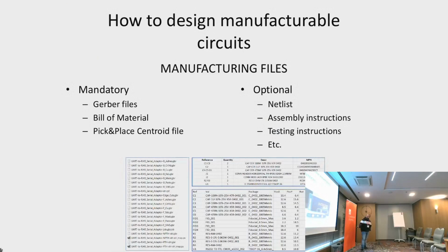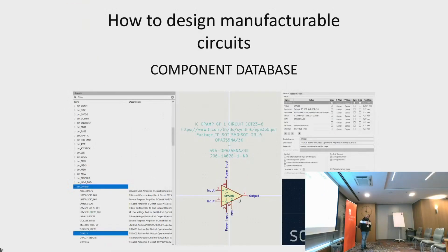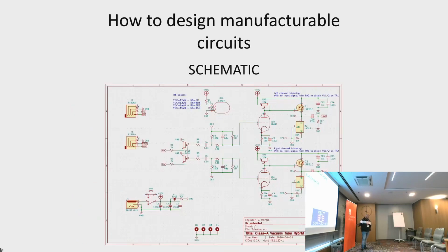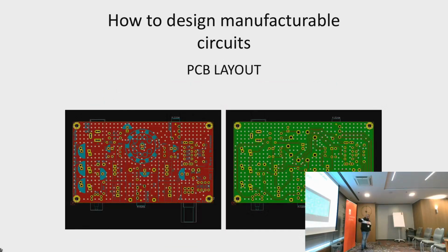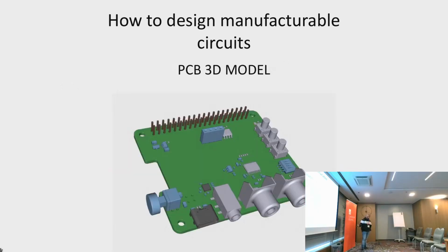Yeah, I forgot to mention that. Let's go back. In the footprint editor, you can attach a reference to the 3D model of the component. That is taken later on by the layout tool, when you can export the complete 3D model: the board with its shape plus all the 3D models of the components. And this is what you get at the end. Okay. Yeah, I was missing the tube in that screenshot, but that's a different model, I think. No, it's a different project.